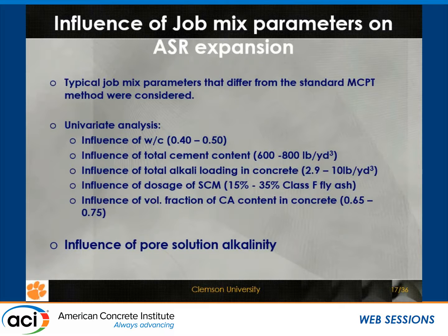One of the big differences between the standard test method and a job mixture is that the concrete mixture recipes or the proportions are very different. And if you look at every other test that we do on concrete, whether it is compressive strength, flexural strength, or even durability tests like chloride permeability, we actually test concrete that is going to be placed in the field as is. ASR is one of the few tests where we actually have tests on a recipe that has nothing to do with what's out in the field.